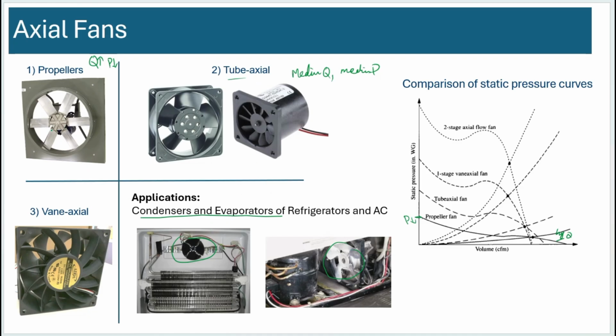When you look at a propeller fan, basically it'll look like it's almost fully open. Your ceiling fan is basically a propeller fan. There's hardly any pressure change that fan causes, but it creates a lot of flow in your room for cooling things in your room. But these fans have to overcome some pressure, so you won't see that much open area in these fans. They mostly have big blades, so they have to overcome a lot of pressure.